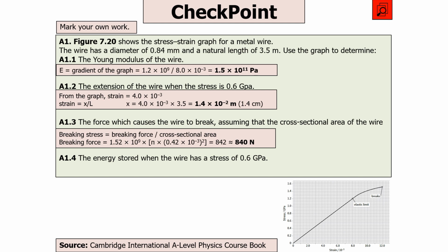Now how can you work through the force? Well, the breaking stress is the breaking force divided by the area, so the breaking force is going to be the stress times by the cross-sectional area.